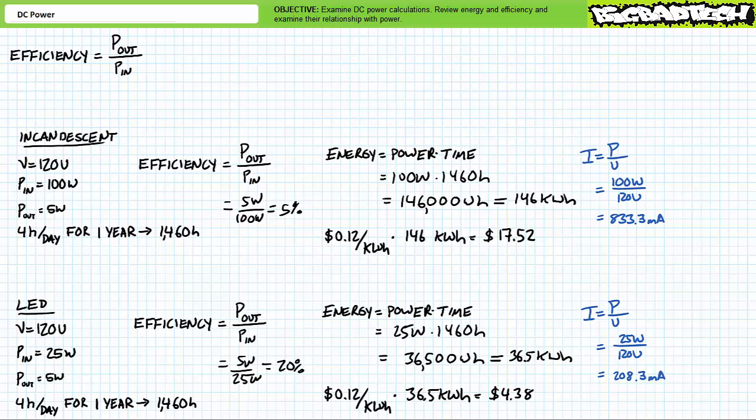As this example is intended to illustrate, this really highlights the clear superiority of the more modern efficient LED bulb over the hopelessly inefficient incandescent bulb. Not only does the LED bulb use less energy over time, thereby costing the operator less, it also draws less current. This may not seem dramatic. However, consider the design and construction of the electrical infrastructure meant to support a large number of facilities, all drawing smaller amounts of current. Given a reduction in current requirement, the size of the wiring, thus the weight and expense of the larger transmission system, can also be smaller.